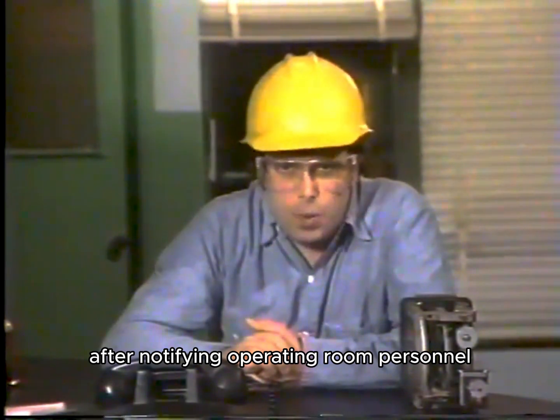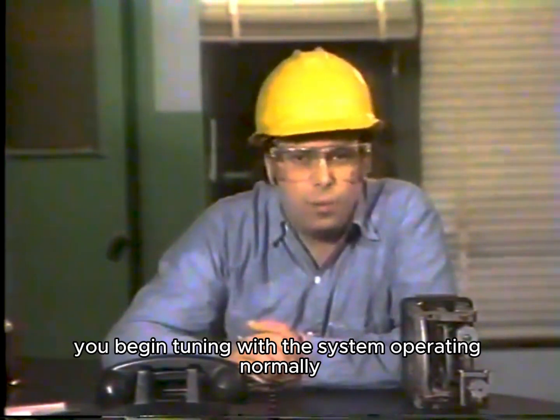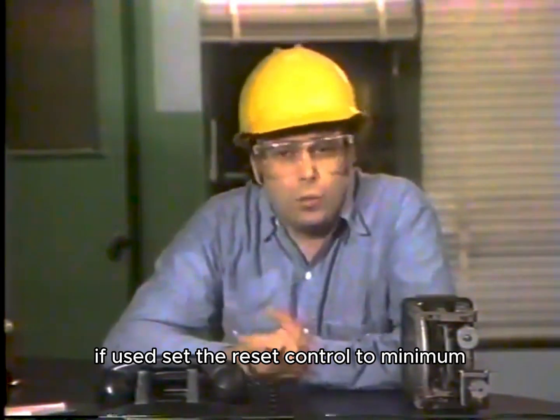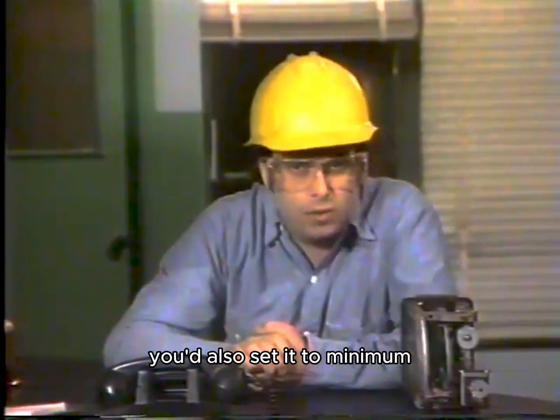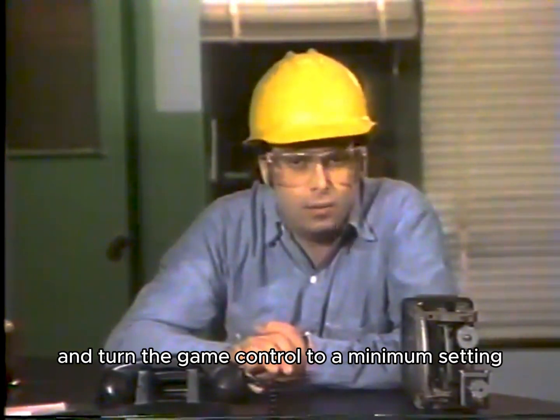After notifying operating room personnel, you begin tuning with the system operating normally and the controller in manual. If used, set the reset control to minimum. And of course, if there was a rate control being used, you'd also set it to minimum, and turn the gain control to a minimum setting.